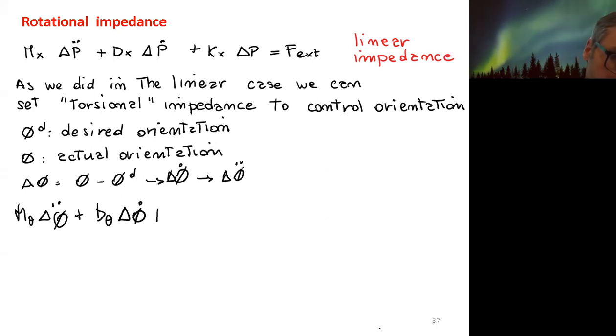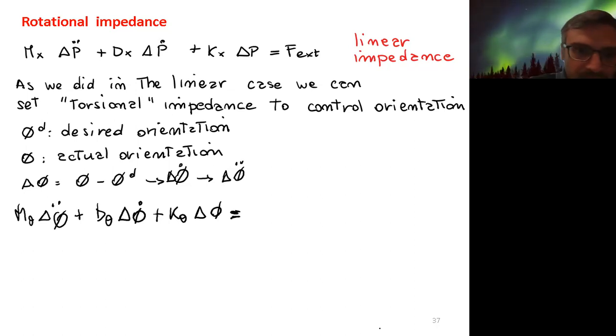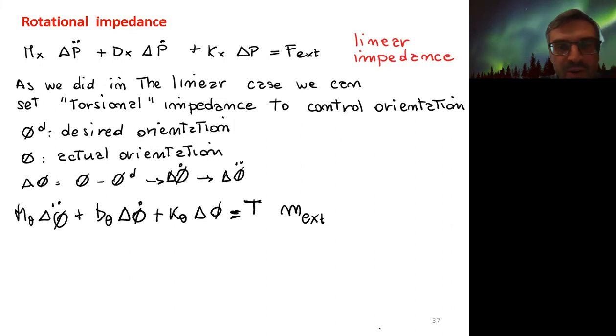delta phi dot plus delta phi. And here, remember, we need to do the Jacobian transpose. Sorry, instead of using the Jacobian transpose, we need to map the moment, let's say, that is defined in the Cartesian space, and we need to use the matrix T. But remember, the matrix T is for the velocity level, to map Euler rates into angular velocity.